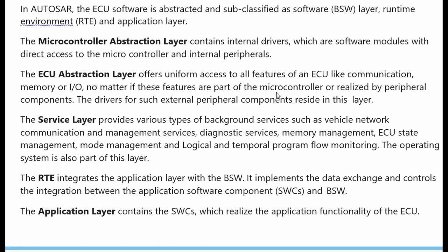Okay. So next one is the service layer. It is the major part of the BSW, and it is the highest layer of the BSW, that is basic software. It includes operating system functionality, vehicle network communication and management services, memory services, diagnostics, ECU state management, and mode management.